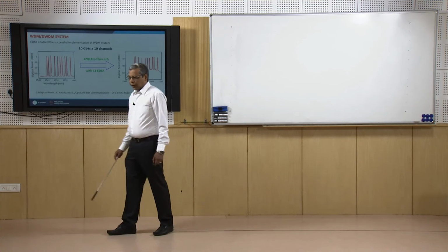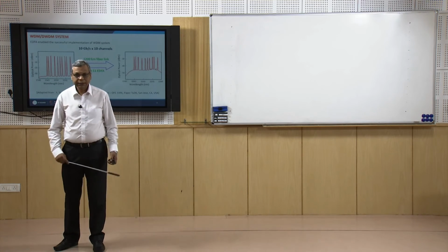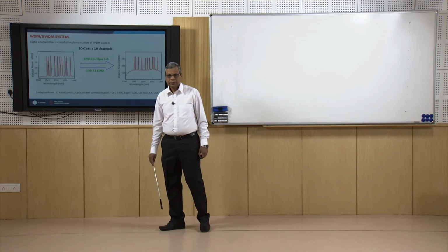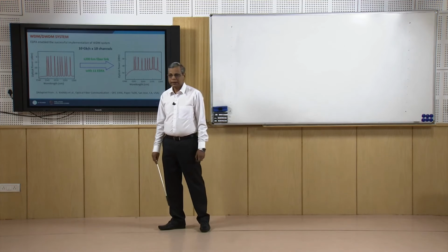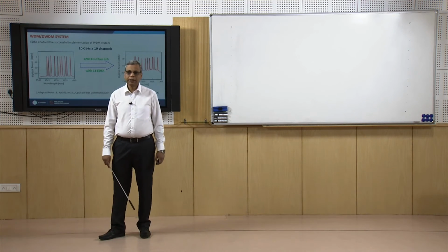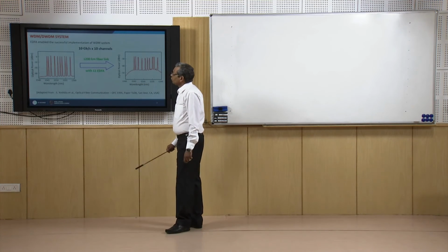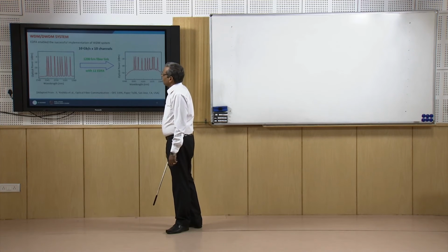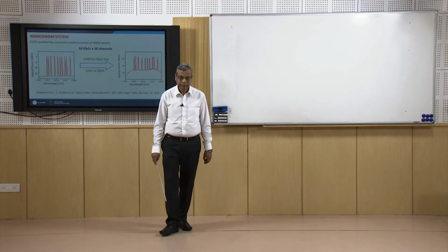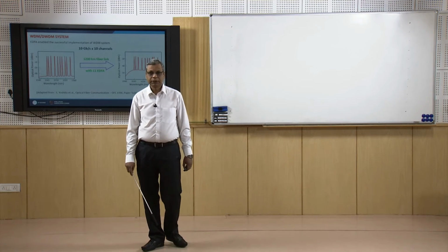Then if I come to the system, we can send several wavelengths in the fiber, and each wavelength can carry data independently. So, we can have a wavelength division multiplex system, and erbium doped fiber amplifier EDFA has enabled the successful implementation of this WDM system and increased the data rate of a given fiber many folds.